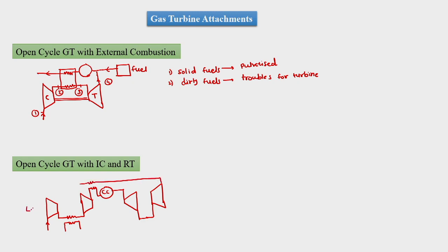we are trying to have a low pressure compressor, then we have a high pressure compressor, then we have a high pressure turbine, and we have a low pressure turbine, and here before going to that we are also adding certain heat. So in this portion, air is getting compressed using the low pressure compressor, and then it goes to the high pressure compressor.